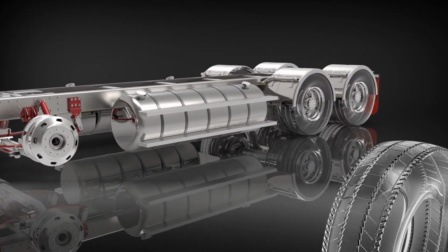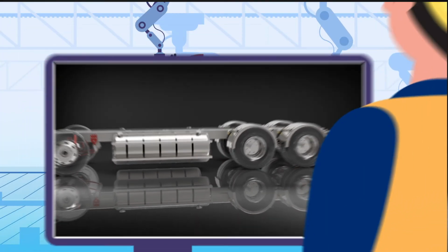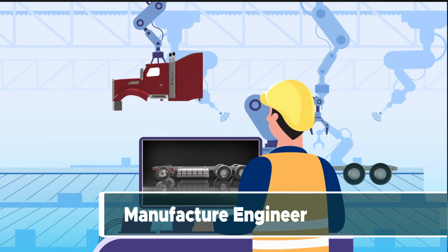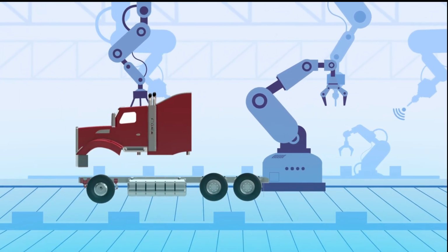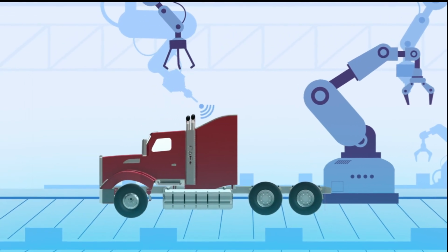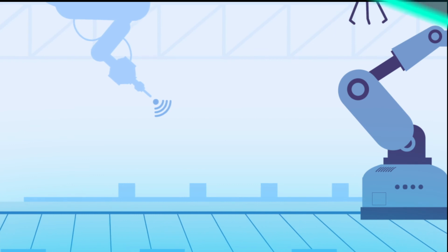The production planning and tool design consists of planning how to mass produce the product and which tools should be used in the manufacturing process. Tasks to complete in this step include the selection of the production processes, determining the sequence of operations, and selecting tools such as jigs, fixtures, metal cutting, and metal or plastic forming tools.